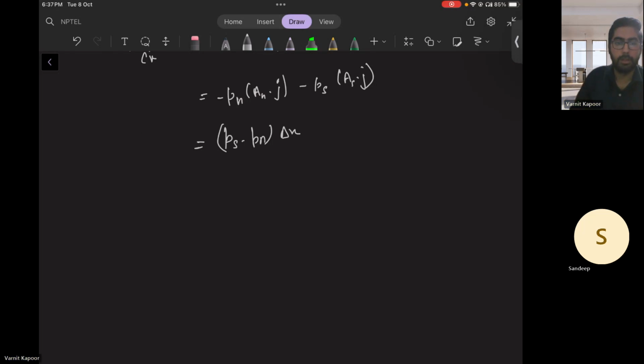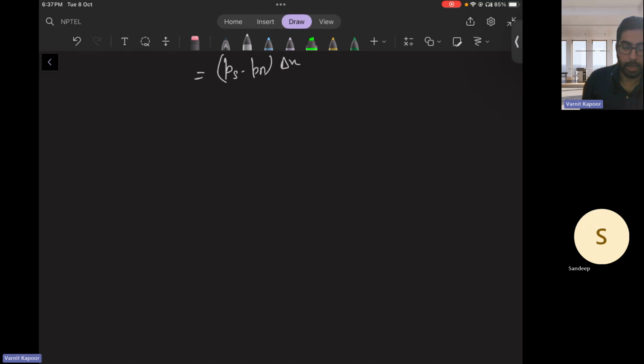You have written it. Now our equation had other terms as well, which we have already done. The pressure discretization we had not done, but the viscous part, that is just the diffusion part, and the convection part we have already done in our previous tutorial. So after putting it back, our equation will look something like this: AP UP, because instead of phi, our variable is u. We want to calculate u.